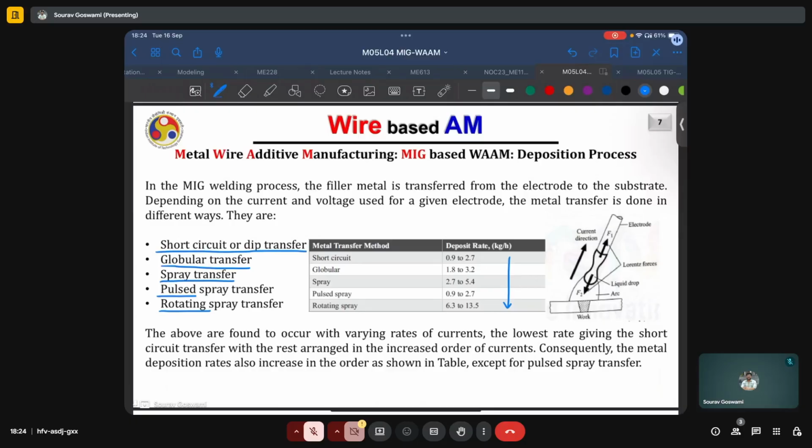And it is because of this high deposition rate of material, as well as the compatibility of the WAAM process even with highly conductive or reflective materials such as copper and aluminum, that it is acknowledged as a truly industrially scalable process. Because for industrial needs, we cannot always have methods like, say, selective laser melting, which will have very fine layers and very long print times.